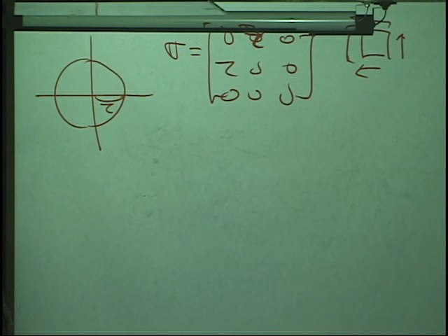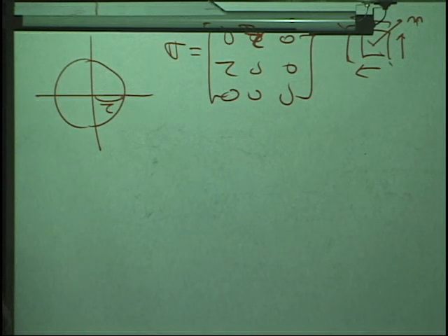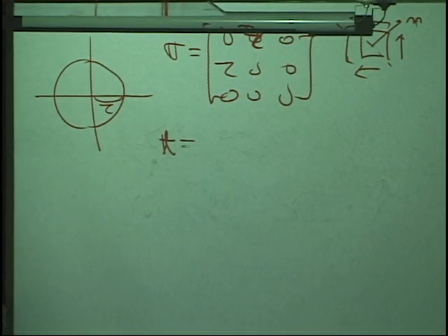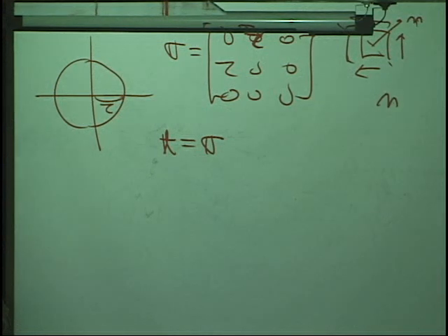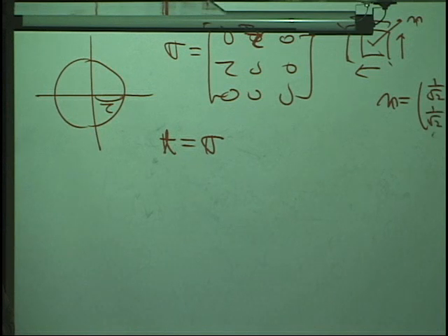Now, what kind of stress component will we have in the 45 direction? Let's try to calculate it using that formula. In the 45 direction, let's call this the n vector. How do we calculate the traction on that vector? First of all, what is the n in components? 1 over root 2 and 1 over root 2 and 0, right?